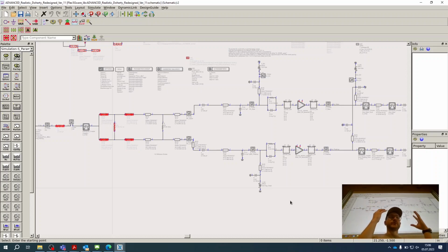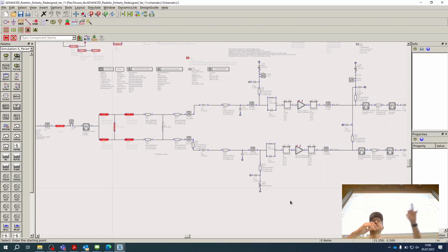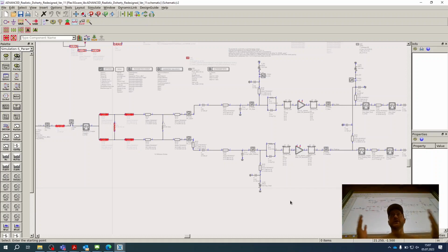And because we're able to apply a larger drain source voltage, and because they seem to retain the carrier mobility of their predecessors like silicon carbide, or of, for example, GaN or gallium arsenide, they seem to have a higher band gap, allowing us to produce a larger RF output power. Now, with larger RF output power, you have the thermal resistances, you have a lot of heat sources, because a lot of the DC power that you give to the device is being lost, and lost means it's going to heat. And for that, we think about the packaging.